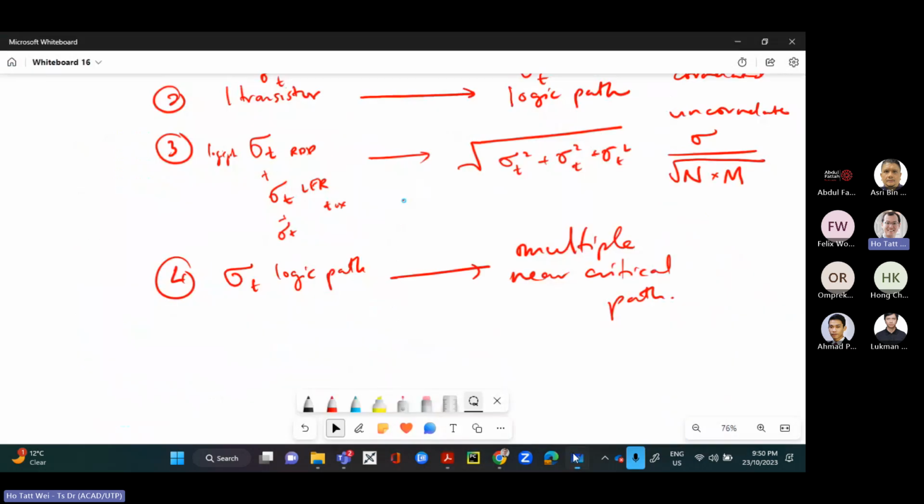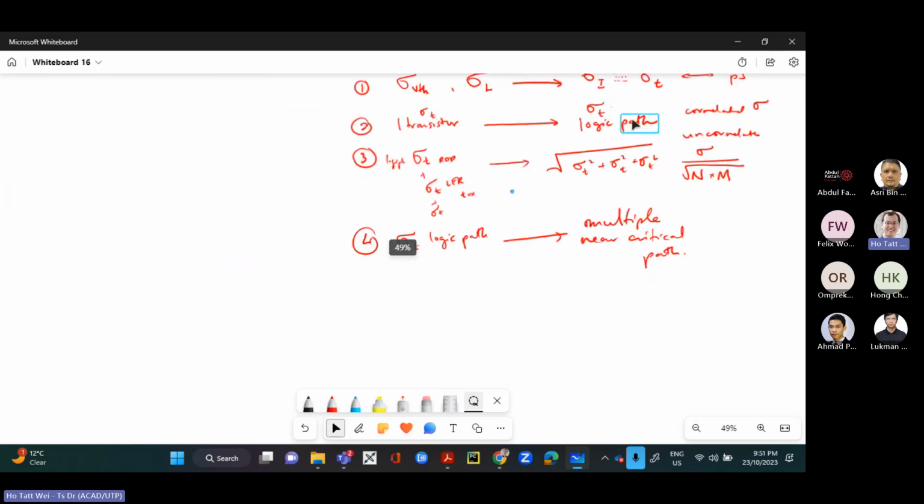We've now gone through how to estimate the effect of process variations, statistically compute the effect of process variations. How does it impact the critical or near critical path delay? And as I mentioned, the main point is you are setting things like your maximum frequency that you can operate at, and you're also looking at what would be the range of delays, or the range of performance, that you can expect from your chip. That's what we're looking at now.